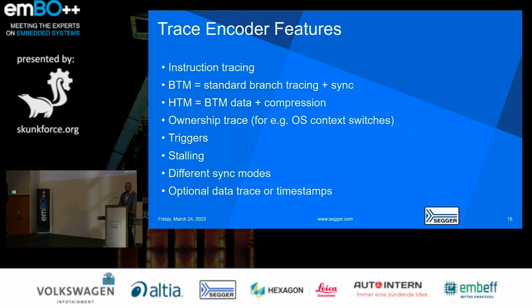Then we have different sync modes, because the trace stream has to be synced from time to time. And here it's even configurable, so you can either turn syncs off completely, have them count trace messages or packets, or just count CPU cycles or the half-word instructions that have been executed. And we have optional data trace or timestamps.